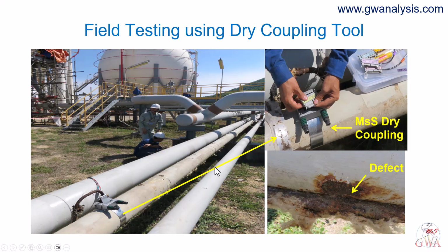Stripping insulation is usually the largest single cost of the inspection and often the reason an inspection does not happen at all. With this test, we demonstrated that guided wave testing finds defects in corrosion under insulation. That is the application where this technique earns its place. Because CUI is hidden by definition, you cannot see it and you cannot easily measure it without removing the insulation you are trying to avoid removing.